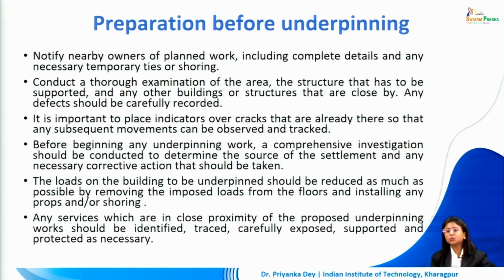So, let's say due to uneven settlement in the soil, some cracks have developed in the structure or the facade, and we are going for a new foundation because our soil is settling and we are having structural damages being formed. In that case, when we start doing the process of underpinning, let's say due to this subsequent movement, new cracks may form. So it is important for us to signify which were the cracks that were formed beforehand and which are the new ones that are appearing because of this underpinning process that we are undertaking. So we have to definitely document and clearly mark all the previous cracks so that no new ones emerge throughout